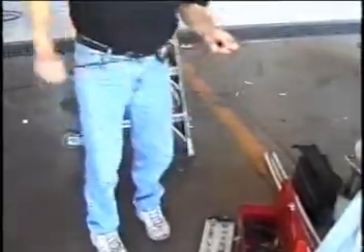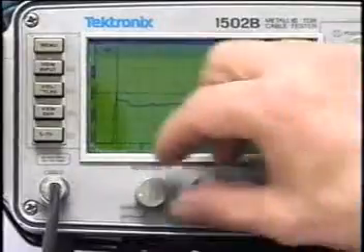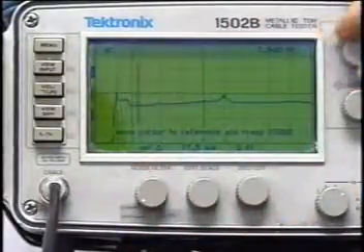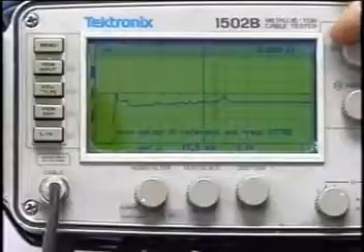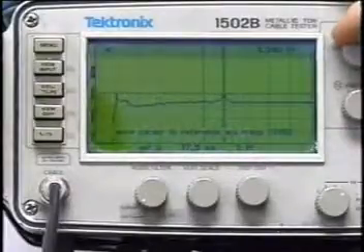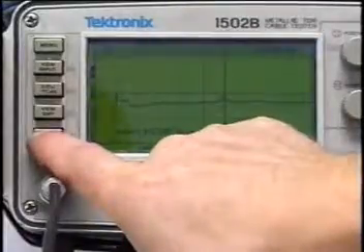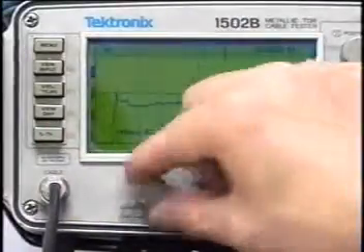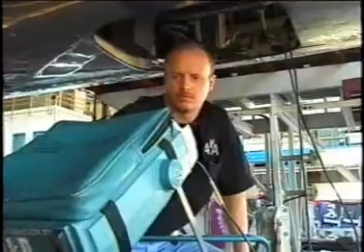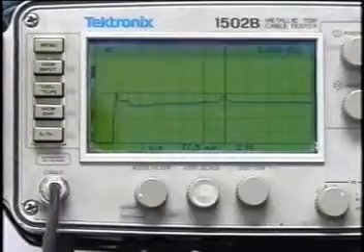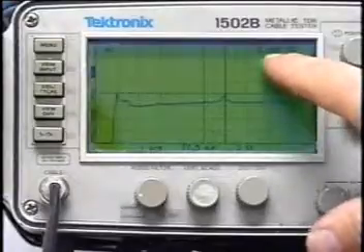When using an adapter cable, you must compensate for its length. Turn the noise filter control to horizontal set reference and position the display's cursor at the distance where the adapter cable connects to the aircraft cable. Push store, then turn the noise filter control to 1 average. The TDR now adjusts for the length of the adapter cable and reads the beginning of the aircraft cable at 0 feet.